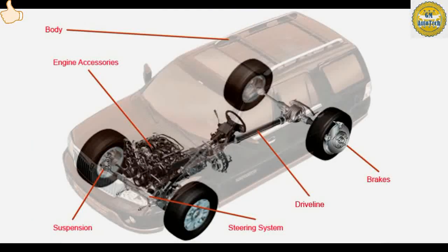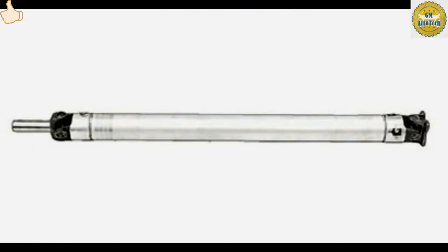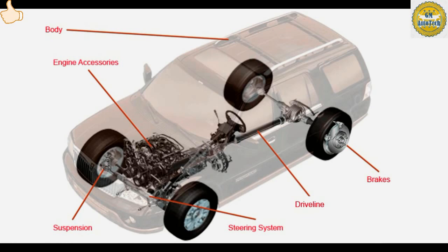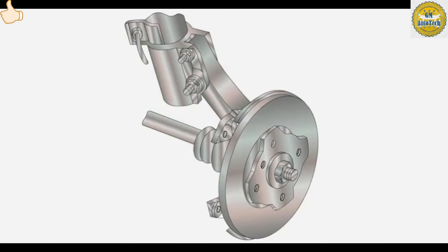A momentary clunking noise from the rear of the vehicle during acceleration could be caused by worn U-joints. Excessive rear differential backlash could also cause a clunking sound, especially when shifting from reverse to drive. A howl or whine could be caused by gear damage in the differential. A squeal, grinding, or thumping noise may all be attributed to the brake system.